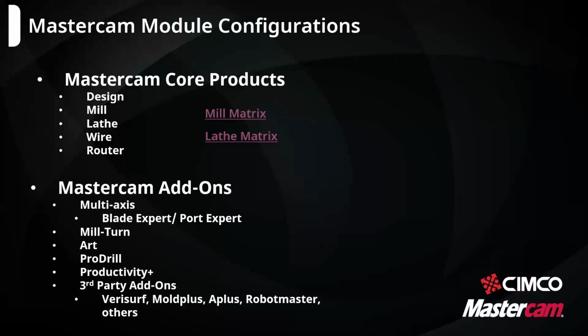So companies like DMG Mori, and I think Mazak has one now, where the CNC machine can actually deposit metal in an additive sense and then go back and remachine critical areas on the same machine. They have a whole set of toolpaths geared toward laying that material down before you have to go back and machine the critical areas.